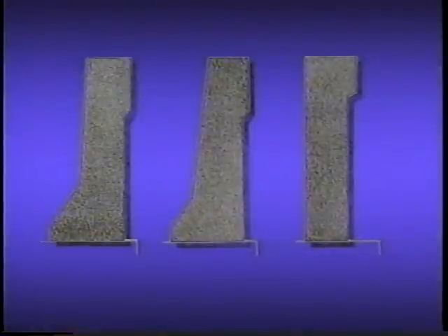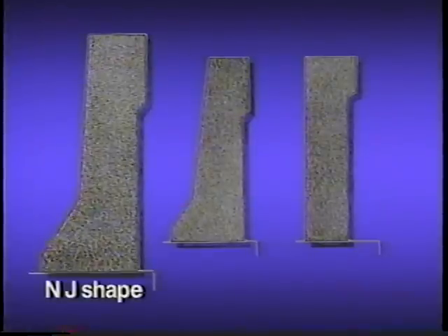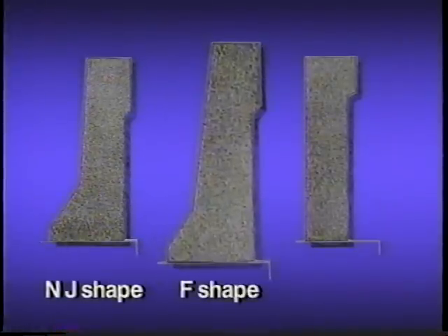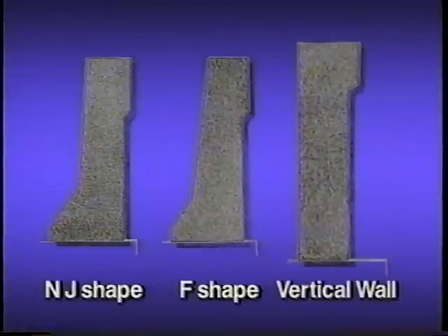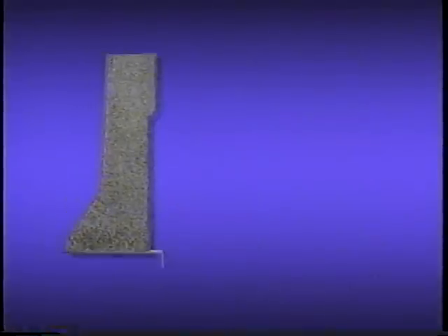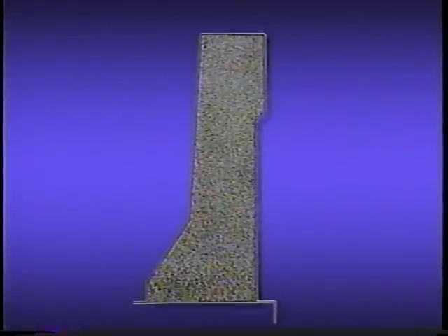Recently, several concrete bridge railings have been tested to determine if they meet the AASHTO PL2 criteria: the New Jersey safety shape, the F-shape barrier, and the vertical concrete wall bridge railing. The concrete safety shape barrier, also known as the New Jersey barrier, is without a doubt the most popular bridge rail in use today. One reason for the popularity of the concrete safety shape is that it effectively prevents vehicles from penetrating the rail while being nearly maintenance-free.